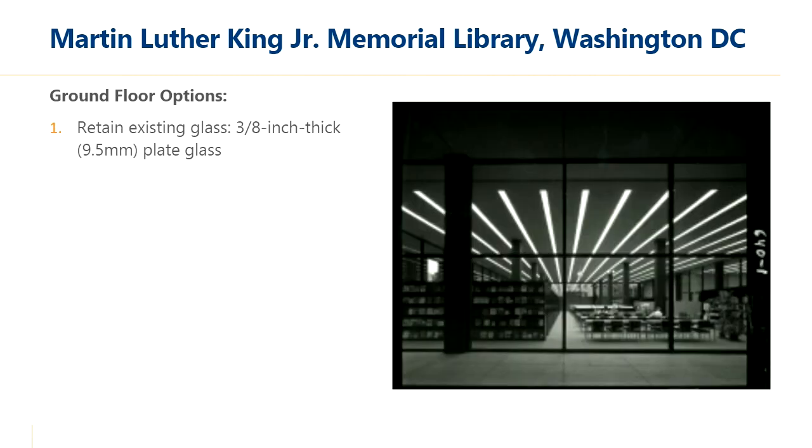So the first question was, can we save any of it? Can we save any of the original plate glass and maybe even use it on one facade? This option was pretty quickly dismissed as the original glass alone didn't meet the requirement of safety glazing, and it was deemed impractical to remove, ship, and laminate the existing lights.